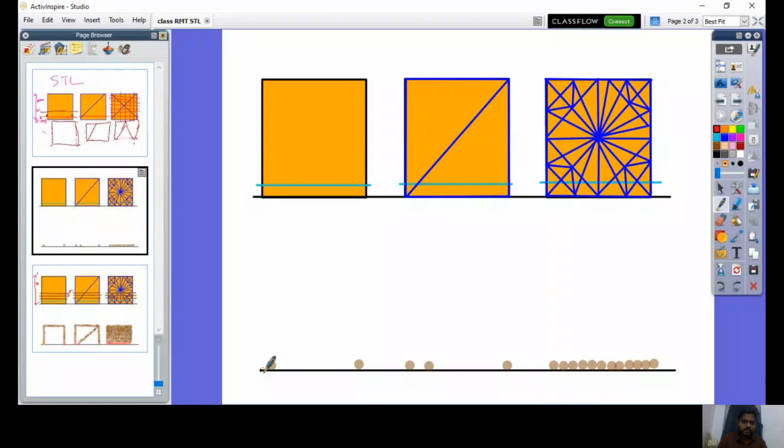The machine will also have a 0,0 position. From this information, the machine gets to know that the first point is at 2,2 and the second point is at 4,2. So the machine nozzle will go from the origin to 2,2 and deposit material. Then the second information is at 2,4, it will go to 2,4 and deposit material.